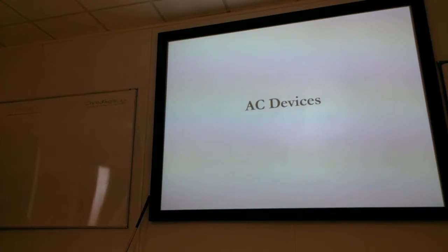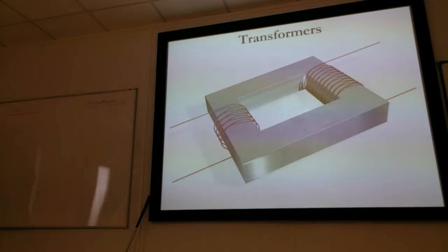Okay, so we've got AC electricity, we've got it turning motors, we've got it all sorted out with our reactance loads, our inductance and our capacitance. What are we going to do with that AC? Well, firstly, we can easily transform it to different voltages. With a simple winding of transformers like that, if you've got double the number of turns on the output side, you get double the voltage but half the current, because the relationship is constant.